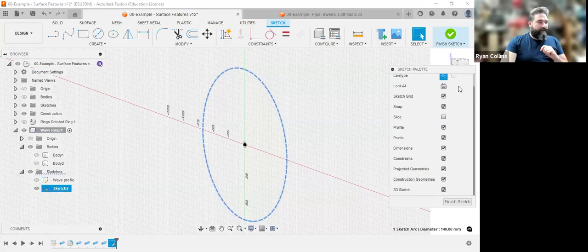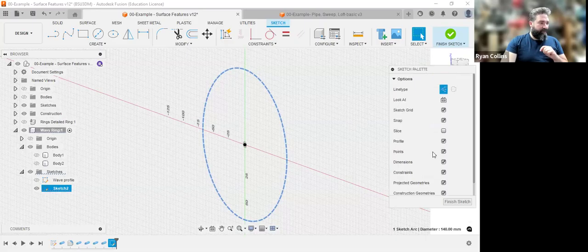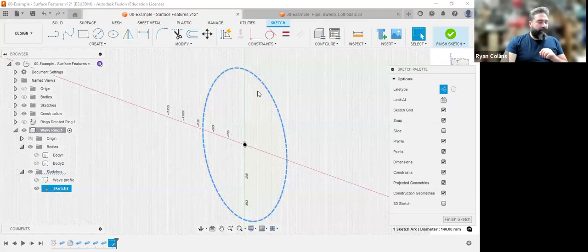If you look at the toolbox for the sketch palette here, where everything normally is, I don't know why mine is slightly smaller at the moment. There's a checkbox all the way at the bottom that says 3D sketch. Normally, this is unchecked because when you're drawing, this will help lock everything to the plane you have been working on. However, I actually want to build off of that plane. To do this, you just simply check that box.